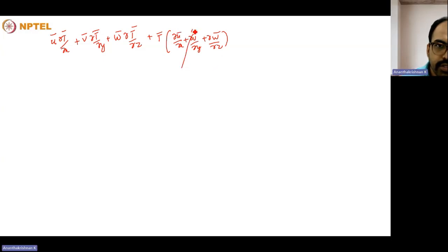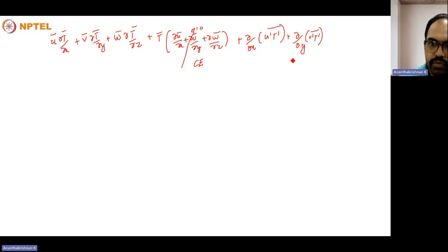So this is the continuity equation that will be equal to 0, plus the fluctuating terms that will be dou by dou x of u dash t dash average. I beg your pardon for some confusion that happened in the starting of this problem where I told that this particular term will be 0. No, it won't become equal to 0 because that particular term will remain. So there's slight confusion regarding the identities that we have used prior. So that will be w dash t dash bar. That will be equal to alpha into del squared t bar.